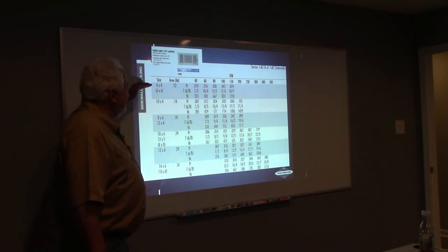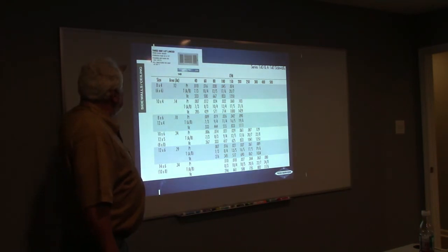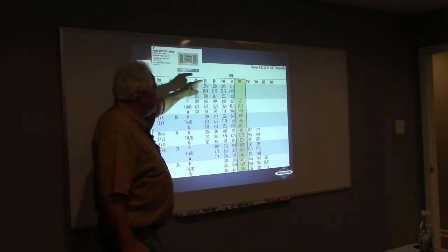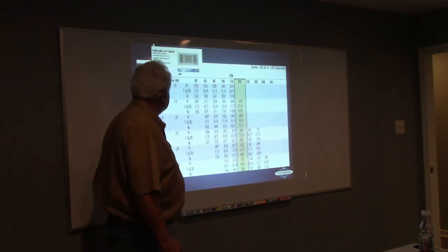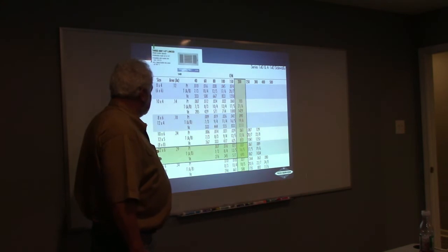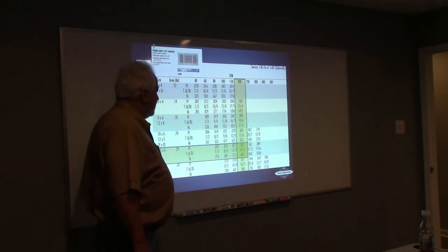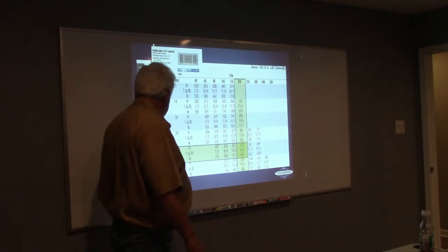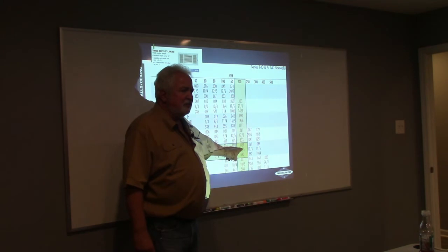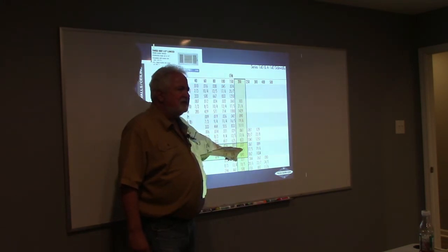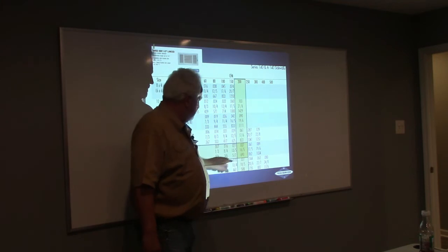So here we go. Let's look at this, and maybe we want to put 200 CFM, because that was that 190 we needed to move through there, yes? 200, so that's the CFM. Let's try a 12 by 6. When I look at that, 200 CFM through that 12 by 6, my static pressure is 0.037. And we said we wanted to be 0.02 to 0.03. So this is probably a little more resistance than what we'd like to see. Okay, well, let's look at this.